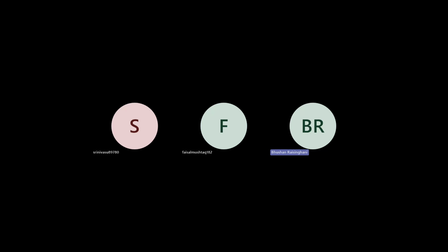Okay. Now, if it is a tall building and it is acting as a cantilever, then it is a flexible building. So high-rise buildings which are small in plan and larger in height will behave like a cantilever, whereas a building which is smaller in height and more in plan will act with shear behavior. So many different literatures and textbooks use this. You can refer to the book of